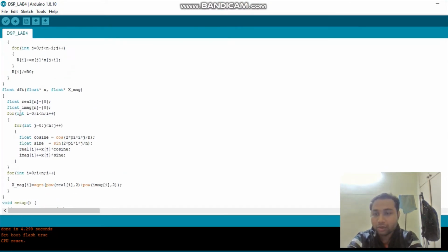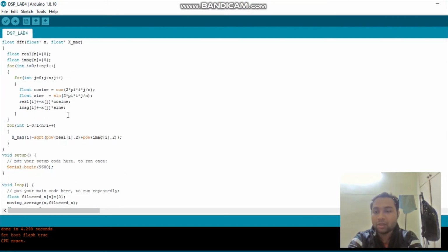So now how are we going to find the pulse rate? For finding the pulse rate, when we have that frequency domain signal, we are going to find the first maximum peak. In a signal there is a case where a maximum peak can be repeated, but we will take the first maximum peak, as after that it will repeat and be periodic, so we take the first maximum peak.